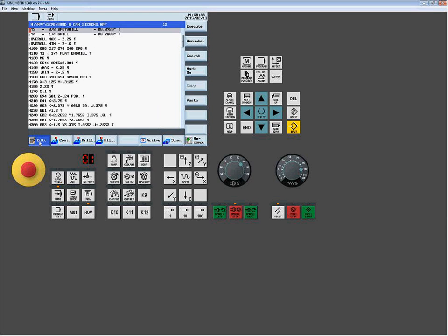So what I'm going to do, and I'm just going to put it somewhere just below my tool change, is I can do a statement called TOFFR equals. I'm going to put a negative whatever the radius value is. TOFFR sounds like a funny kind of statement, but really what it is is tool offset radius. So we're adjusting the tool offset's radius. I can use this as an L, TOFFL, and then I can adjust the length of an offset.